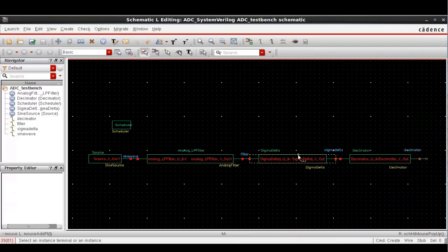The last bit of this demonstration that is currently missing is a scheduler block. That is to say, a block that specifies the invocation rate of each of the subsystems. The scheduler must be manually made by the user. The scheduler is required because neither the C code nor the SystemVerilog wrapper have any notion of time. Therefore, we need to tell the simulator where each of the blocks are invoked.